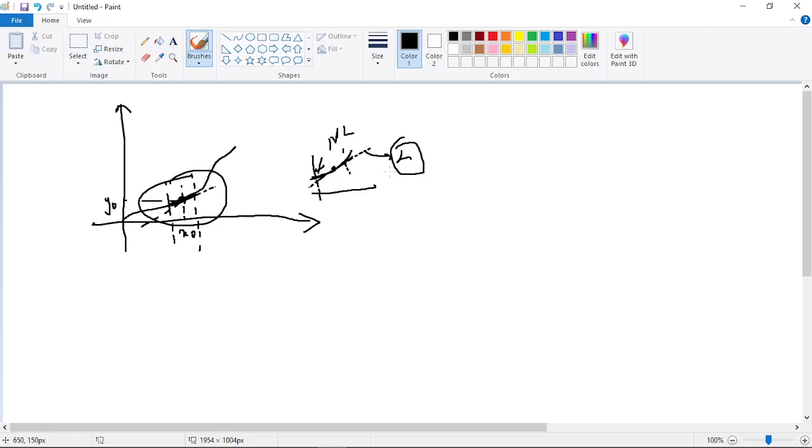Actually, any nonlinear dynamics can be represented in terms of linear dynamics. The major advantage of the linear model is we can apply the classical control theories to design the controllers, or tune the controller parameters, or other things. Okay, so this is the basic principle of linearization.